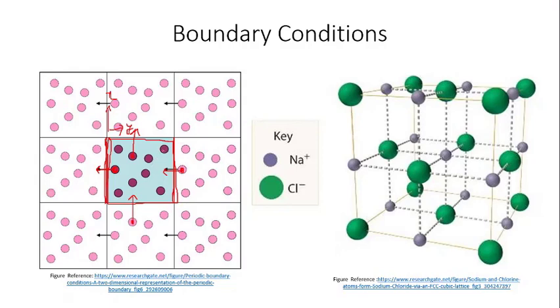So suppose this atom goes outside the boundary at a time step, and this is its final position. Then at the next time step, as the Y boundary is fixed, this will be deleted by LAMMPS. So if any atom goes outside the fixed boundary, that atom will be deleted in the following time steps.